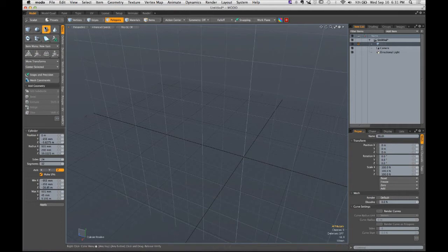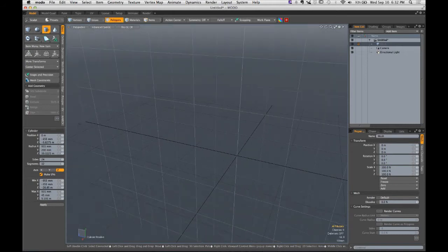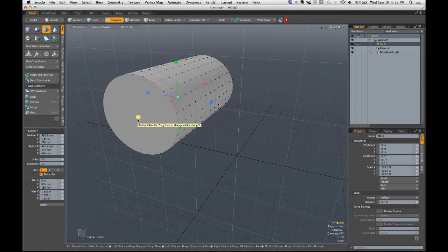I have my cylinder tool active, and I'm going to left-click and drag, and I draw out a circle. We get those very similar and comfortable manipulator handles that will allow us to change the radius of our cylinder. The center one, in my case, the red cube, allows me to extrude that shape along the x-axis and create a three-dimensional cylinder. Before I drop the tool, however, let's look at a number of its properties that will change what's been created. Let's go down and check it out.